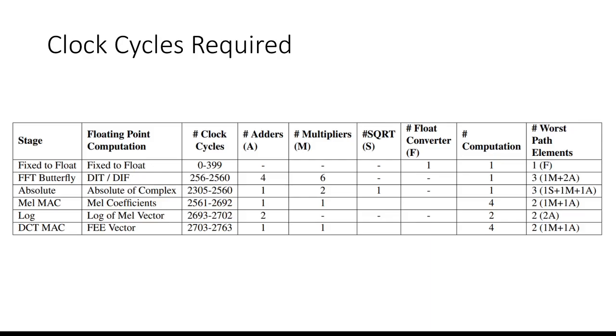The first frame-related feature vector will come at 2752 to 2763 clock cycles. A total of 12 features will be there for each frame. 3 MHz is the maximum operating frequency of the design.